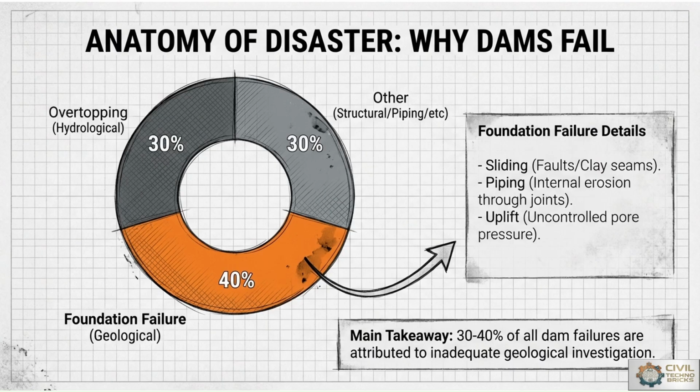Why do dams fail? Why dam fail means just like the disaster. How will the disaster occur from the dam point of view, just like the foundation failure. Dam failures commonly occur due to foundation defects, seepage, slope instability, and poor geological assessment. A weak foundation can cause settlement, sliding, or structural cracking in dams.